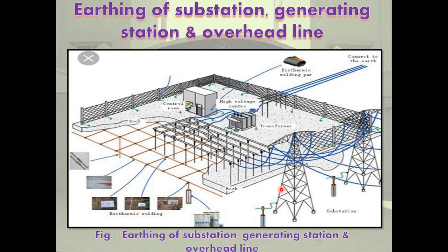Now, what are the switching surges and how do they occur? Overvoltage produced during the opening or closing of circuit breakers are called switching overvoltages. The overvoltages are due to sudden exchange of energy between the series inductance in the circuit and the shunt capacitance of the circuits. Switching overvoltages or surges have a time duration range of 100 to 3000 microseconds and a peak value of about 2 per unit to 4 per unit.